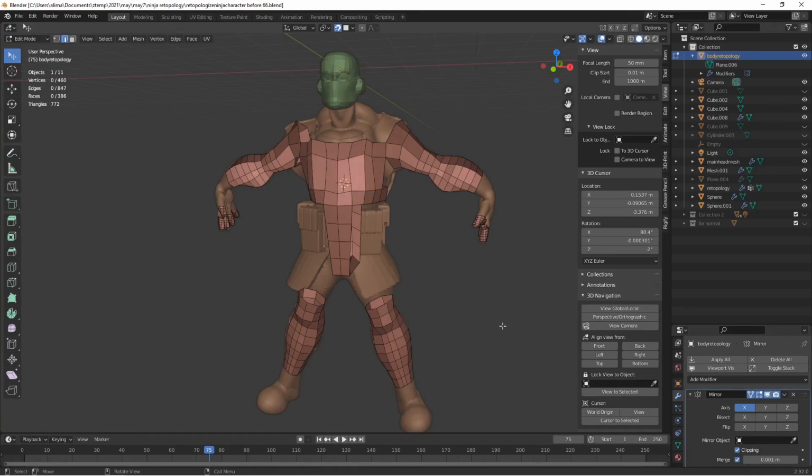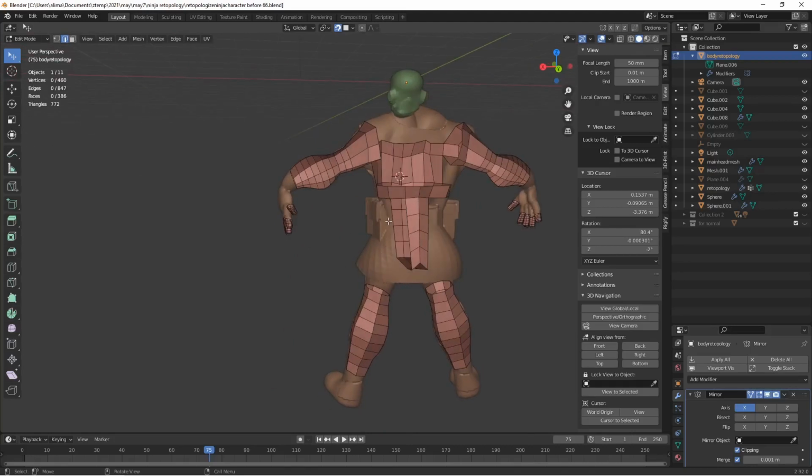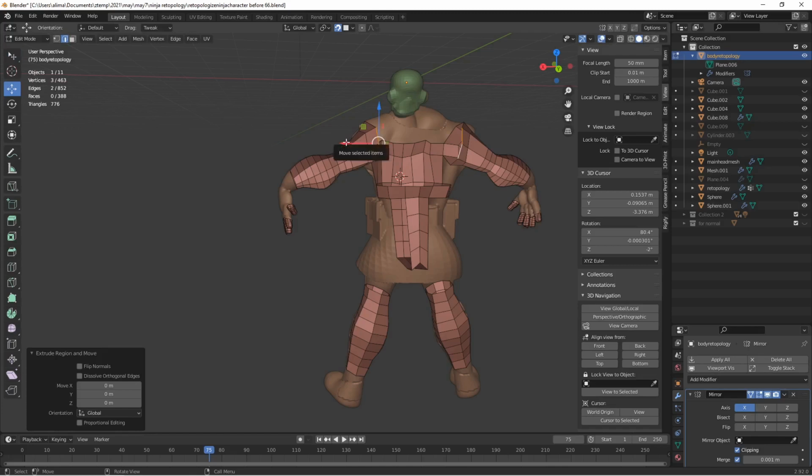Okay, I'm going to hold the middle mouse button to rotate the view. I'm going to select here, hold Shift, then press E, right click. I'm going to our move tool towards the left. I'm going to push these 2 edges towards each other. I'm going to hover here, hold Control, press R, roll my mouse wheel once. I'm going to left click, then left click a second time. So we have 3 faces, like 1, 2, 3, and then another 3 here.